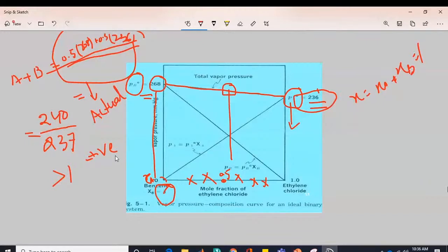The other components whose boiling point is higher, like 90 and 100, will definitely condense and come down. Those which have a low boiling point will rise and go to the top. This is where the separation happens. That's why we call it flash distillation.